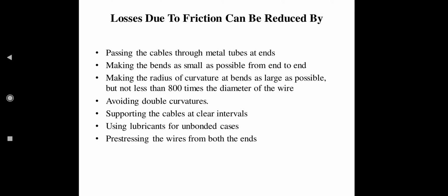Supporting the cables at clear intervals. Supporting the cables inside the ducts will reduce the contact between cables and the duct so that the friction loss can be reduced. Using lubricants for unbonded cases: the use of grease or oil can also help in the reduction of loss due to friction.